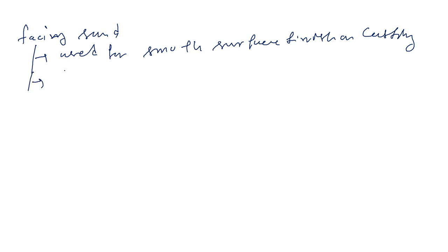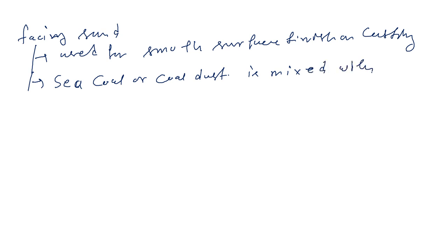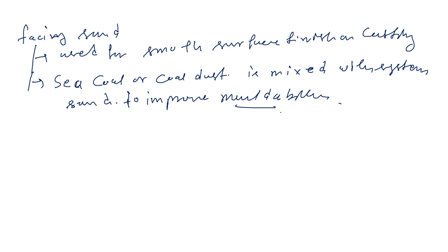These sands are generally sea coal or coal dust, mixed with system sand to improve the moldability and the surface finish. So this is the purpose of this.